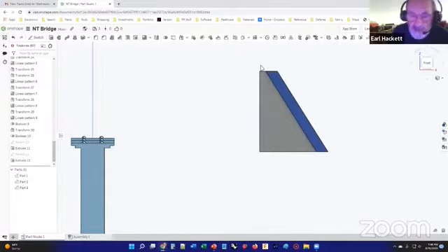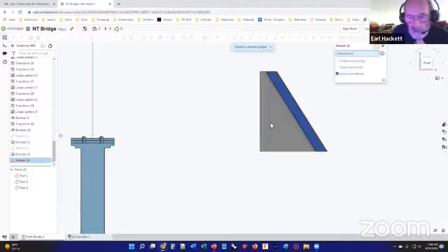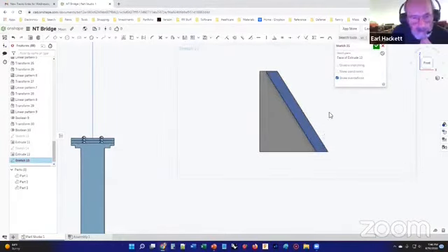And these are 3 by 4 inch angles that they use. So I made this one 0.2. The actual 4-inch length would be 1.2 in HO scale, or pretty darn close to that. So we're going to make another one, just the same thing we do with this, only much thinner. So we're going to do a sketch. We're going to sketch on this surface. And we're going to do another aligned rectangle, exact same deal. To there and down here.